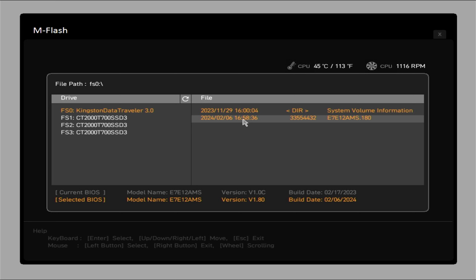So for example, if your system is pretty cool running, or it's a massively high power system, or you just have an air conditioned office or something like that, you might want to just have the fans ticking over at really low speeds like we've got here, and then have them increase once the CPU temperature reaches a certain point. So the CPU temperature is what we've got on the left here. As you can see, our fan has now dropped to 0% or 0 RPM. So that's what we're dealing with here with this fan at the moment. So it's completely silent, not spinning at all.